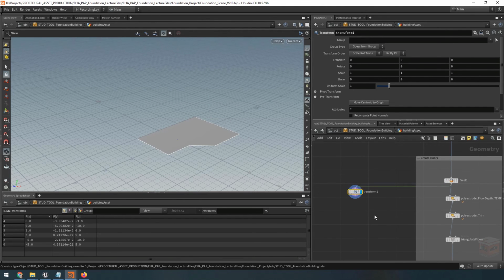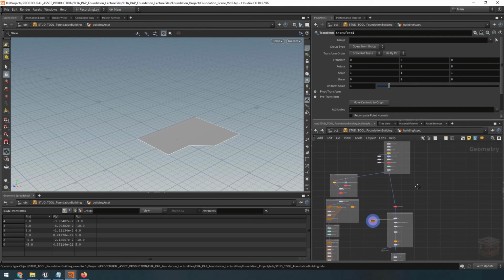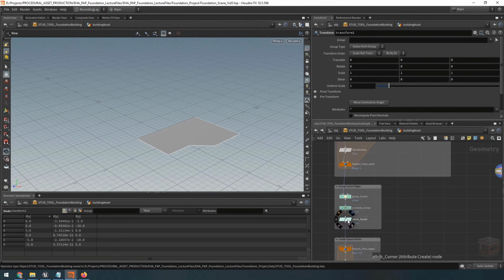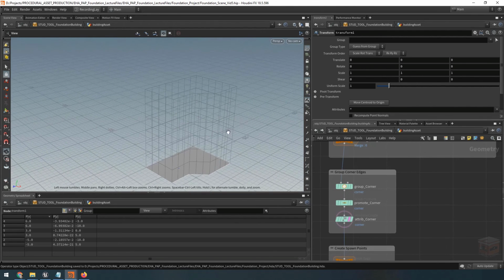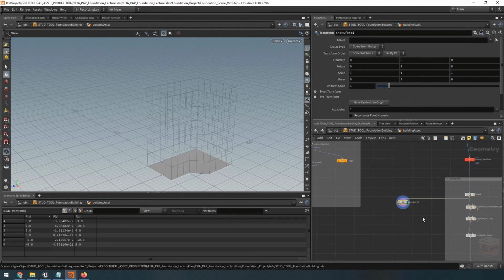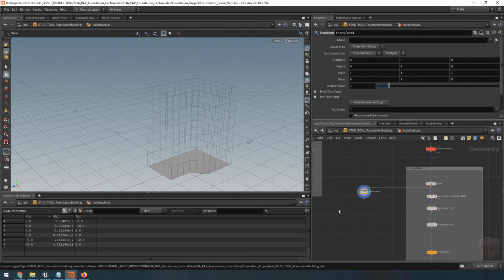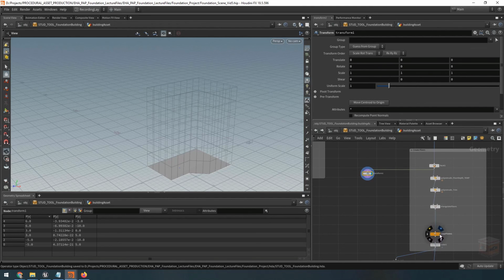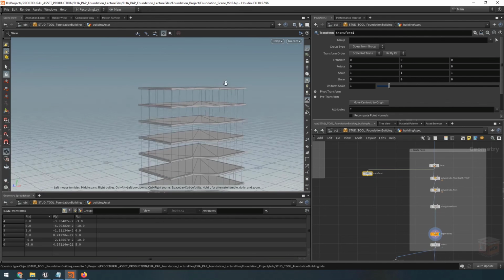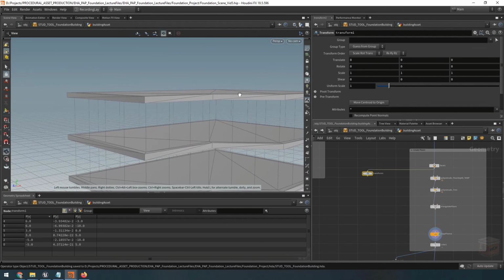So I want to create a railing on the top of my building. So let's have a look at the wireframe again. Let's raise this up to the very top, and we can easily grab that information if we grab the bounding box of the highest point of our floors. So here are our floors. I want to make a railing sit right on top of that. So let's grab this transform node. Let's call this one raise to roof.